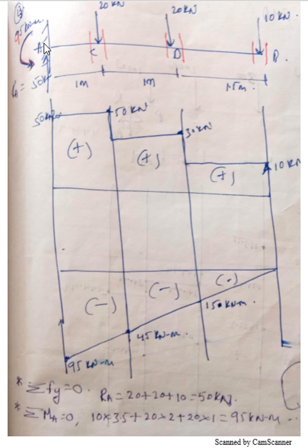Then as soon as I consider the left section, this moment will also come into the picture. When I am considering this moment, it is an anti-clockwise moment. When I add plus 95 and this minus 95, I'll get 0 value. But remember one thing, at the end section the bending moment will be 0. For a cantilever beam, the bending moment at this end section you will always get as 0, because this moment is there because of all these forces only. So when I consider the summation of moment due to these forces and this reaction moment, they will add up and become 0.